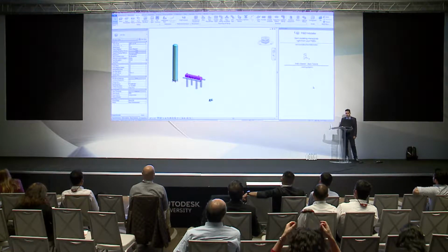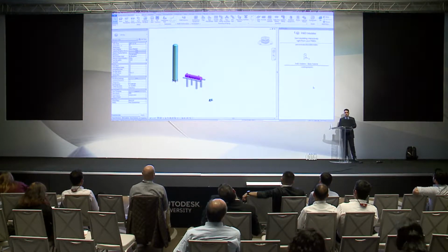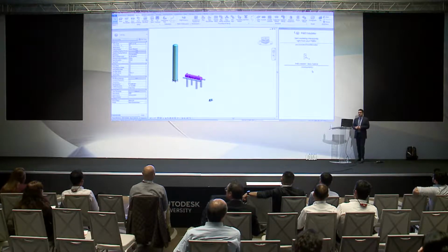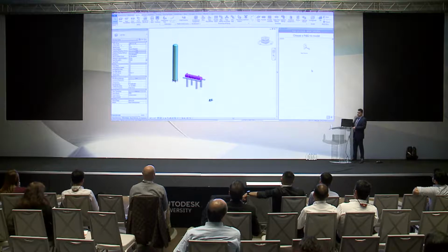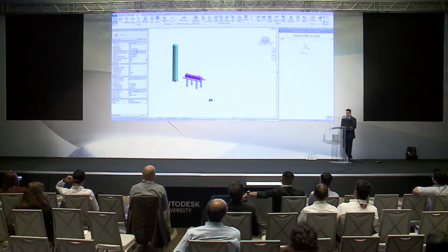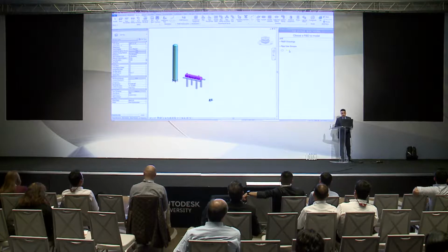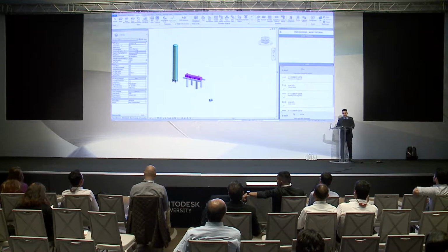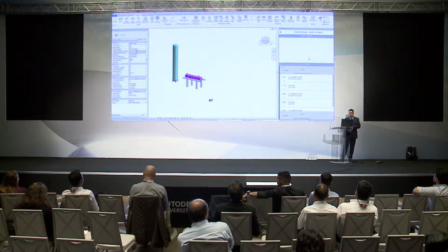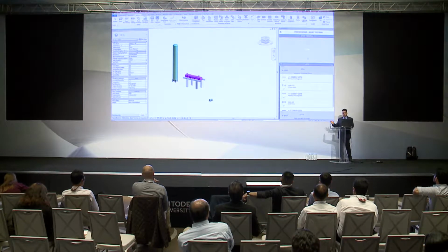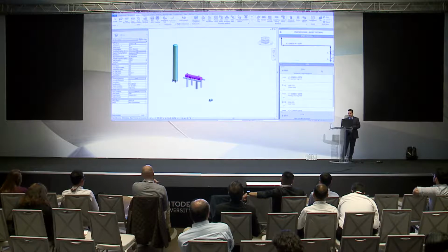It's going to look at all the equipment and all the schematic lines which you need to model. Once the drawing is ready, we're going to start working on that drawing inside Revit. It gives you all those P&ID drawings, all the line dimensions, all the valves, all the fittings coming in from the schematic stage. And you can view the entire drawing directly here in the viewer as well.